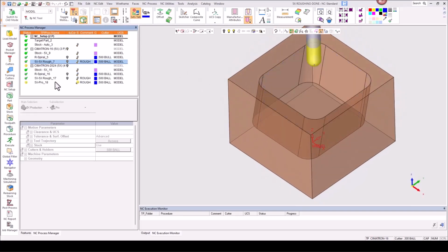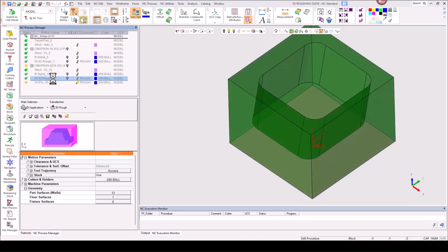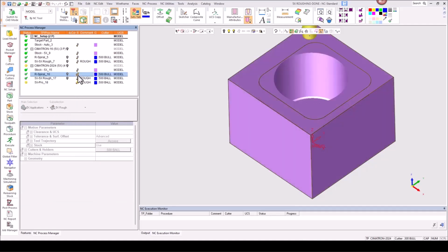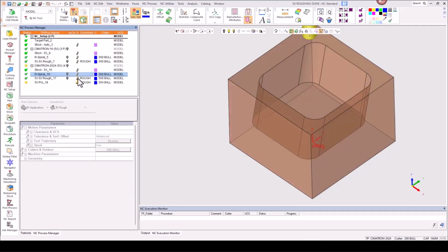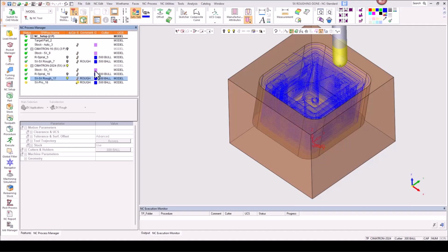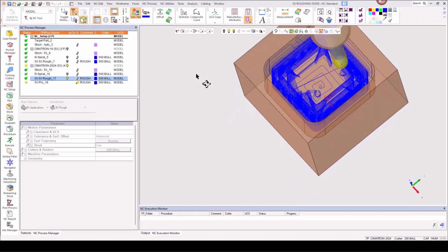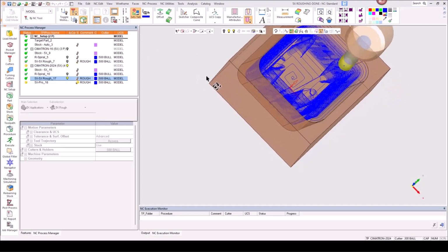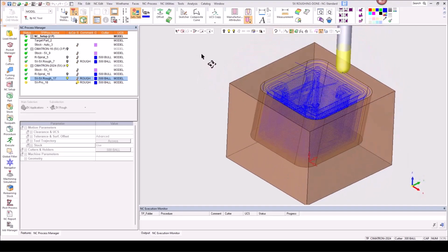Now, in version 2024, we programmed this identical change. Down under stock here, we switch this to use, and we get a very different result. So here's our previous stock again, but this time we get a proper update with the toolpath, and it actually recognizes that that material was gone, and you can see that it doesn't machine all of the area in the middle.